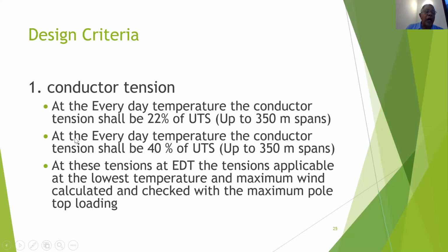Now, at the maximum stress, that is the minimum temperature and maximum wind, the conductor stress should be 40% of UTS.